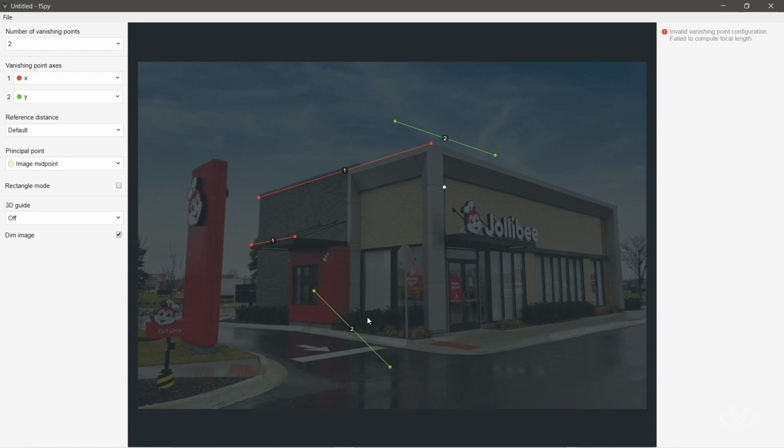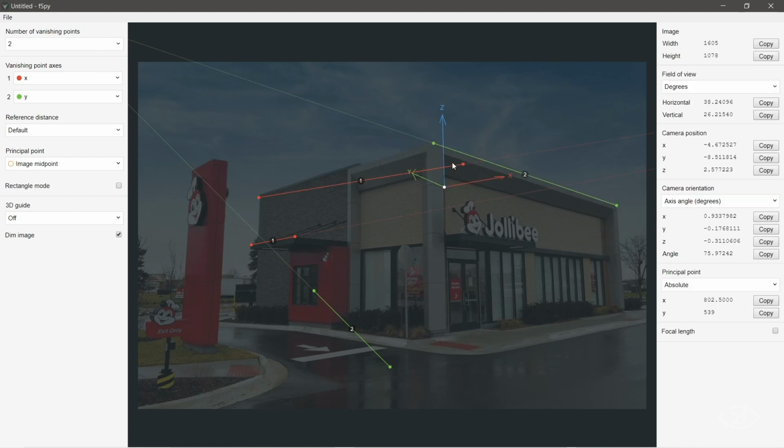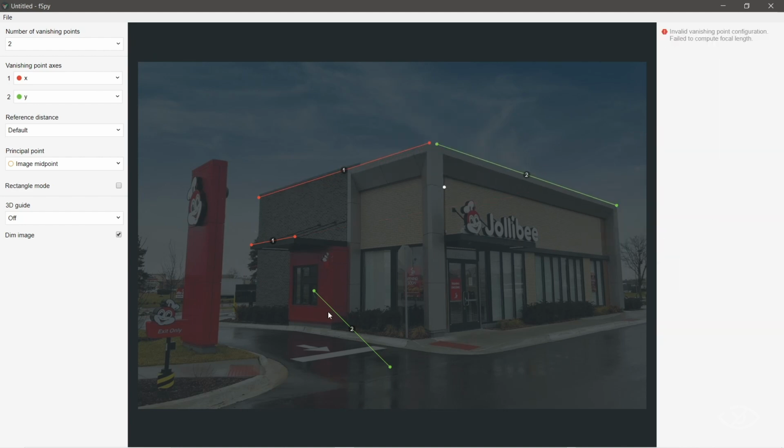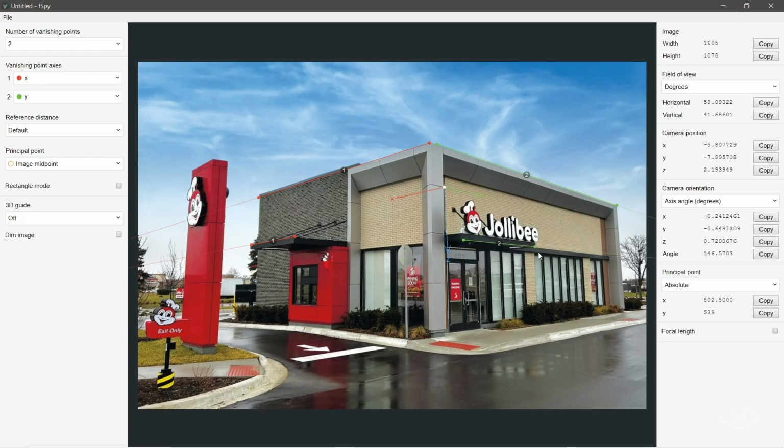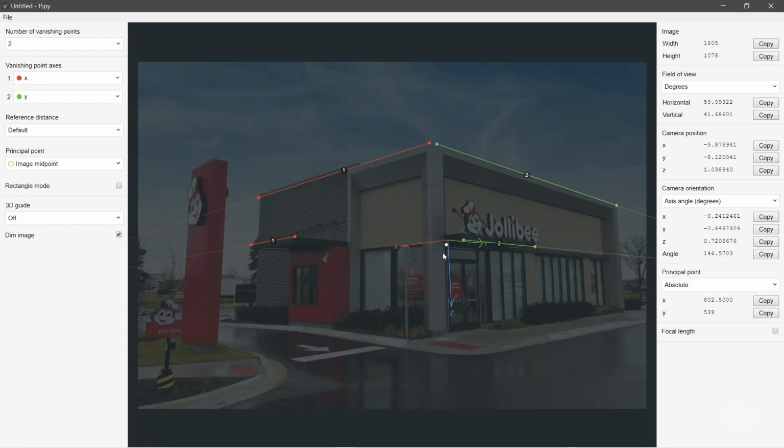As you can see in the vanishing point axis option, the goal is to simply align those axes on the picture. You can press Shift on the keyboard to zoom in. Locations with varying depths are the best place to put the lines. Now, using this cursor, you may verify whether the image's perspective is aligned appropriately. I'm going to position the cursor here.